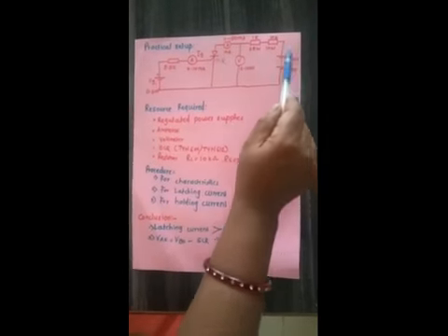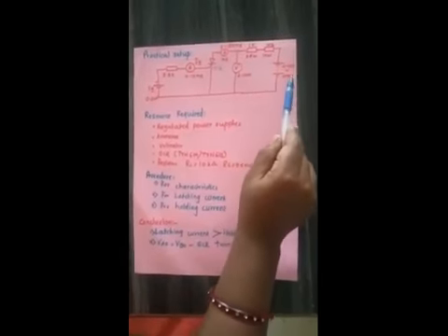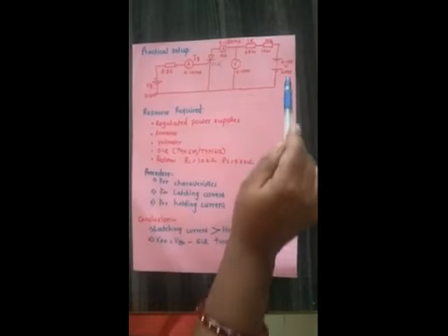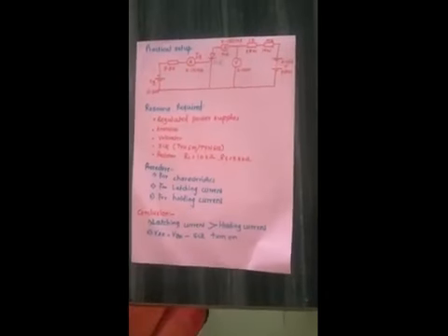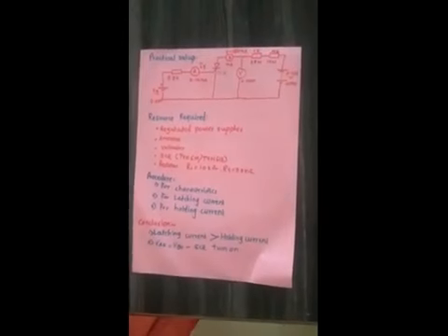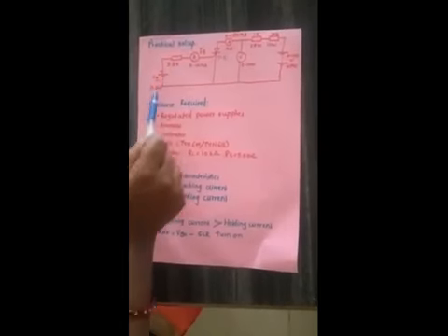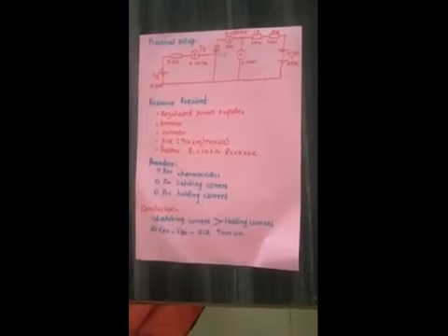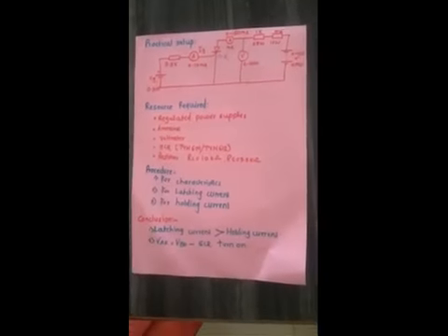After that, here I will connect another power source, another DC source, having the range 0 to 150 volt. It may be variable, hence shown by dotted line. Its value can be varied according to our need, or we can say that according to the applied gate supply, it will be variable. Now this is the practical setup diagram for the VI characteristics of SCR.